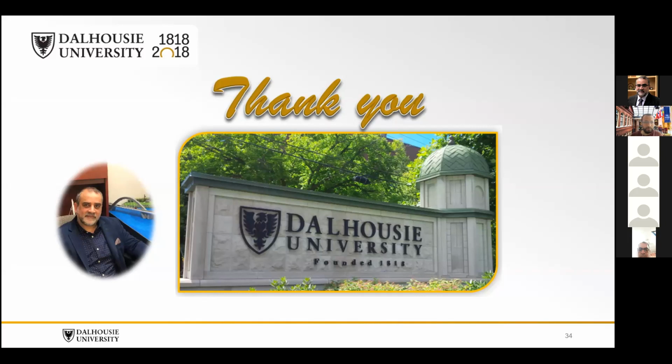Also, we consider the own weight of the tunneling machine itself. And then you have the jacking forces that are being applied. So you have the jacking forces, you have the face pressure, and then also you consider the grouting pressure as well. Have I missed any? I think that's it.